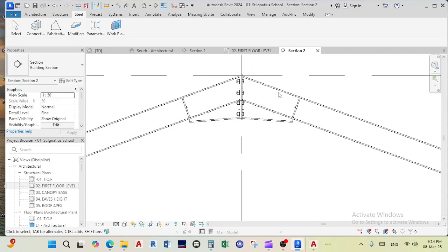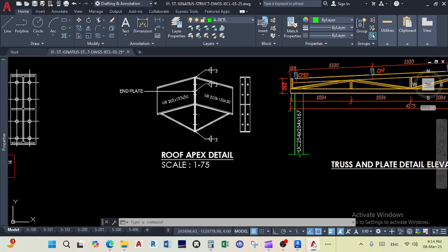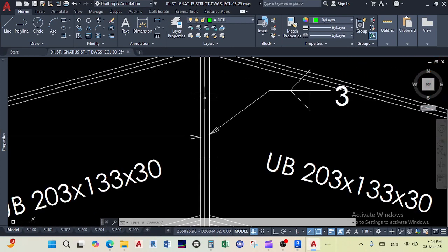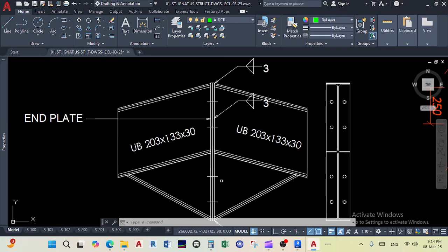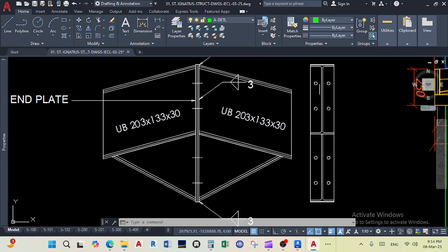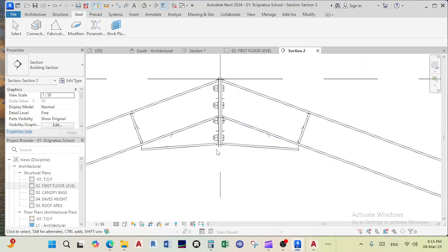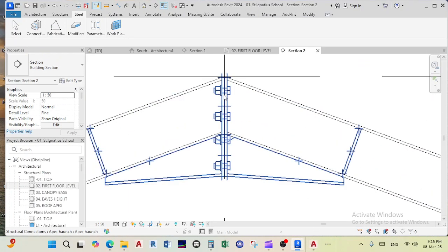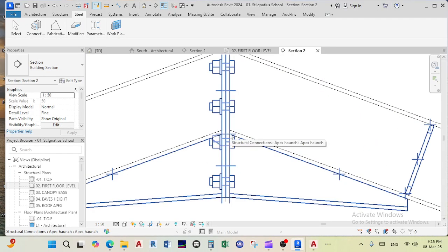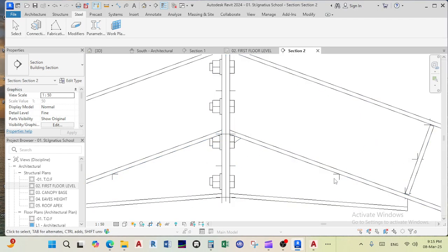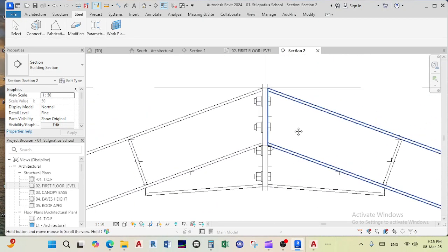You see it. So this and this are pretty close. Although this one just shows those two lines as connection detail as bolts, here it shows as holes. 1, 2, 3, 4, 5, 6, 7, 8. You've got 1, 2, 3, 4 lines, but you're on both sides, so a total of 8. Here it's got 1, 2, 3, 4 also, and it's also got some welds. These are welds. This is how you interpret welds in engineering drawings.